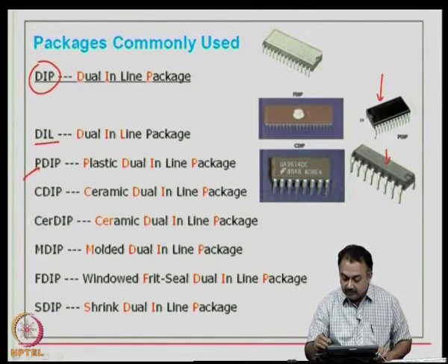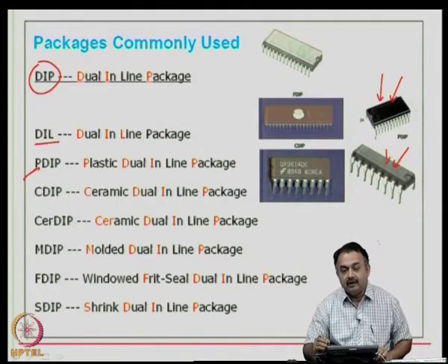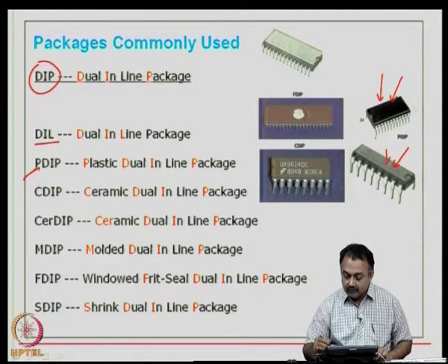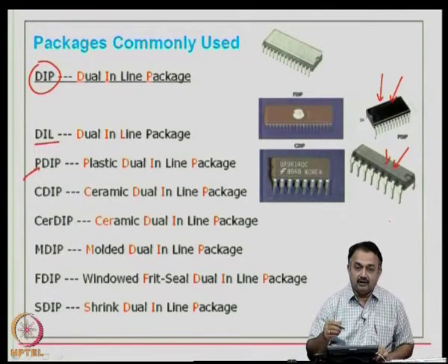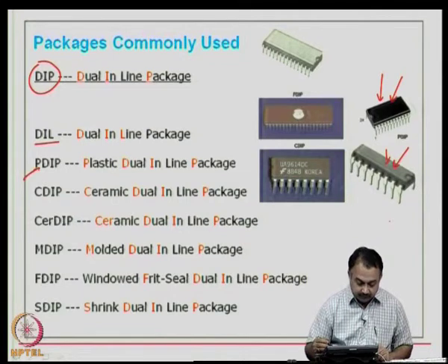The volume of epoxy material to be used in each of these cases are well defined, because you cannot simply add more package volume. So, the thickness is specified, the material is specified, and then these are well cured at certain temperatures, okay, so that it protects the inner bonds, typically a wire bond that is used in these packages.